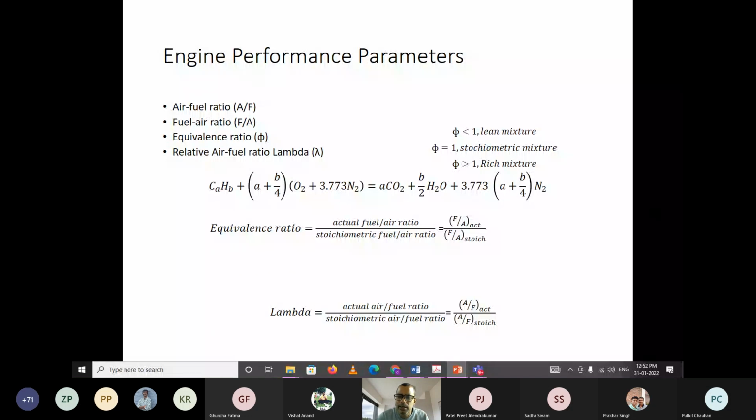It will contain carbon dioxide, water, carbon monoxide, different hydrocarbons, some amount. Nitrogen will come. Your oxides of nitrogen will be there. So these are undesirable products in actual combustion in all three situations. Some of the undesirable products will be more or less depending upon whether a lean mixture is running or a rich mixture is running, on which mixture your engine is running. But undesirable products will always be there for all three conditions.